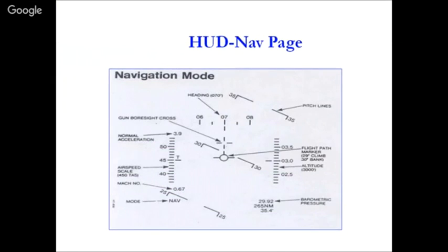all that information which is critical to the pilot at any particular instance is displayed on various pages. Even this is one particular navigation page. You have a lot of pages, there are around 16 pages in our HUD, wherein you can change the symbology which you want to see for a particular thing. And there are page shifters because necessities change. Sometimes you may be in a gimbal lock type of situation, wherein you have lost 1 degree of freedom. Usually you have 3 degrees of freedom. But there is one situation called gimbal lock, wherein two axes become parallel. Now your 1 degree of freedom is lost, then you need some decluttering modes for coming out of that situation. So in those things also HUD helps you.